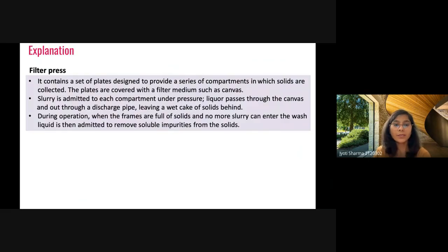You see here, it contains a set of plates designed to provide a series of compartments in which solids are collected. And here the filter media, such as canvas, we can use, and we are giving pressure, and that pressure will push the water through that canvas, and it will go out through a discharge pipe, and that will leave a wet cake of solid behind.